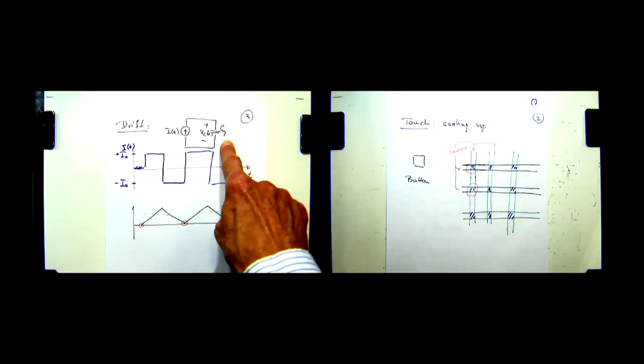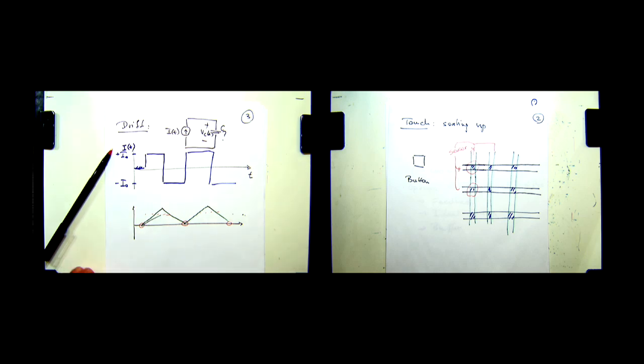Now, one of you pointed out absolutely correctly that that's probably not going to be the case for our circuit. Why is it not going to be the case? Because it's a touch sensor, and the value of this C question mark of the touch capacitor is going to change. That's the whole point of the circuit. When you put the finger there, it's a larger capacitor. Remove the finger, you have a smaller capacitor, and that makes this slope sometimes steeper and sometimes less when the capacitor is larger. So it could be that the slope is going to be less because here you had your finger there, and then afterwards you removed your finger. So now the slope is again going to be faster, like this one, and so you end up here.